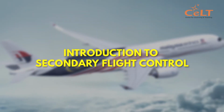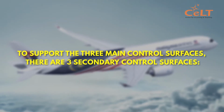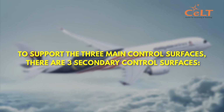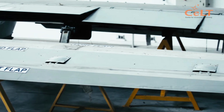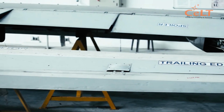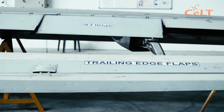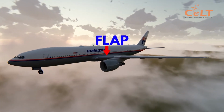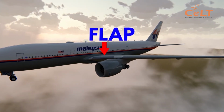Introduction to secondary flight control. To support the three main control surfaces, there are three secondary control surfaces. Flaps, a movable control surface on the aircraft wing, are used to change the amount of lift generated. Flaps deflect downward during takeoff and landing to increase lift. Flaps are retracted immediately after landing to decrease lift.